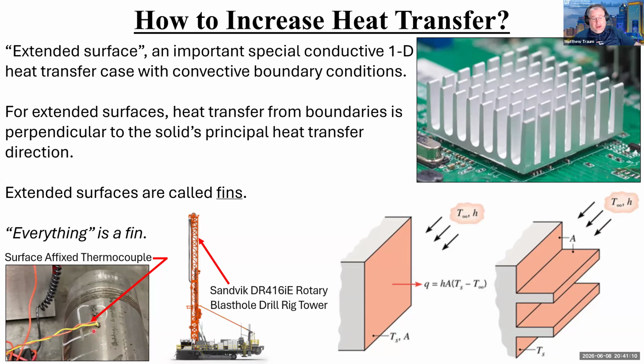Made worse, by the way, since we've talked about critical radius now in the context of the quiz, by the fact that these are usually pretty darn small wires, and a lot of times they'll be insulated for electrical isolation. But because they're below the critical radius, the insulation actually makes them more thermally conductive. So you have these really thermally conductive insulated wires coming off of the spot that you're trying to measure the temperature of, and it will actually mess with the temperature of that spot.